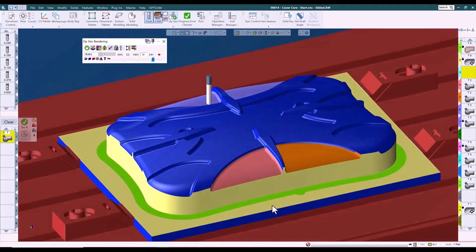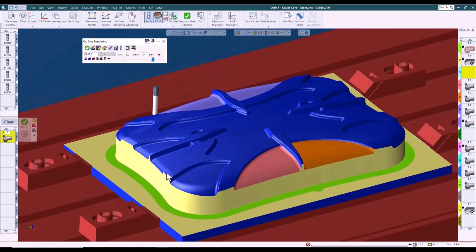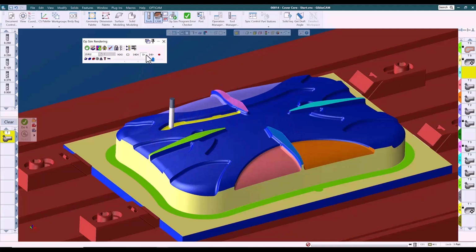5-axis or multi-axis process toolpaths offer us a vast array of additional toolpath styles and patterns, which, though marketed for 5-axis, can output 3, 4, or 5-axis toolpaths and provide options and controls to precisely control all aspects of the toolpath. Additionally, the multi-axis module provides the ability to calculate various toolpaths based on different underlying technologies, such as a